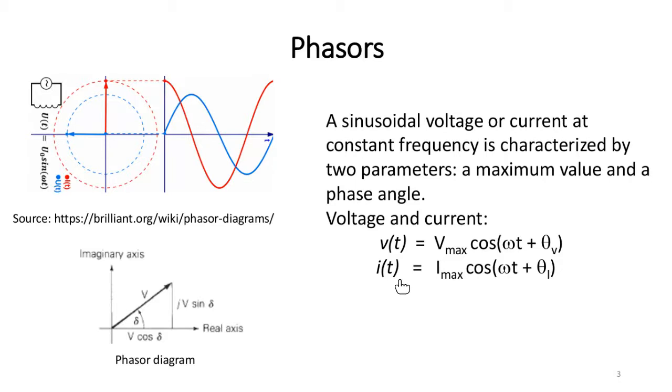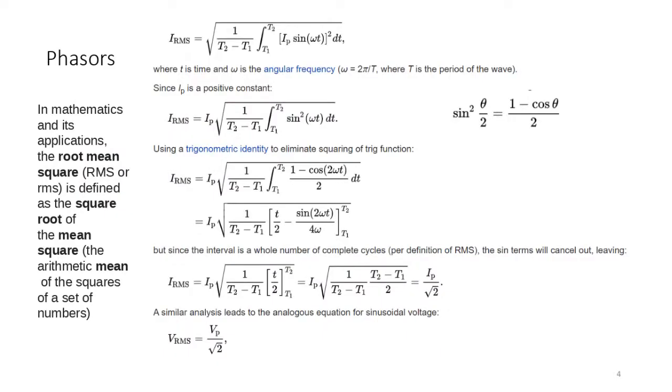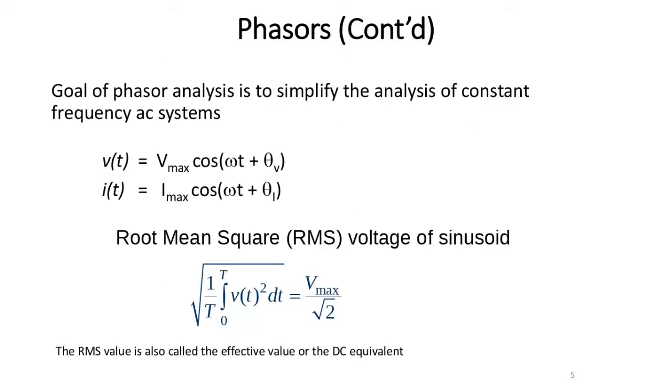That gives you the RMS value, or whatever you write it here. You will see a number. Okay, in problems, for example, you will see a number here, for example, 300. So this is the maximum. Always what comes before the cosine is a maximum value. You will not be asked whether this is RMS or not. Always what comes with the cosine or with the sine is the maximum value. So always the number here is the maximum value, and then you will change it into RMS, over square root of 2.